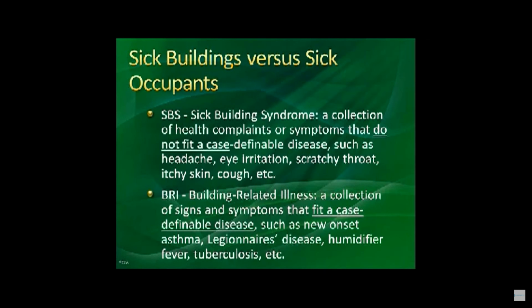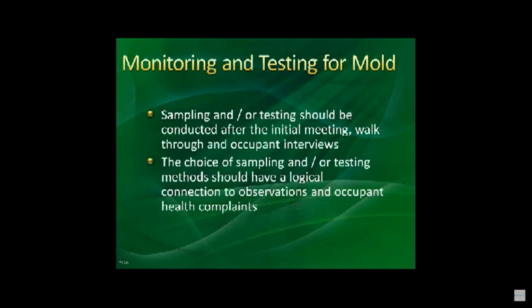When you do monitoring and testing for mold, it's very simple. You take samples or whatever testing method you're going to use, swabs or aerosols, we're going to cover that. You need to choose one of those and have a logical connection to the observation and the complaints.